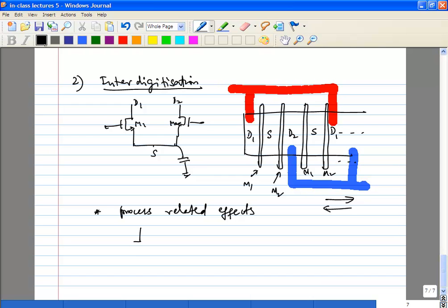Another case where you might want to have it is, let's say, a cascode. You have a common source-drain node here, and you would want to do the same thing. For example, if you have an LNA and any parasitic capacitance here, your VRF is here, IRF flows like this, you want all of that current to flow here. So you want to minimize the parasitic capacitance at that node. You don't want to lose any signal through this path. So you definitely want to interdigitate and reduce the capacitance.